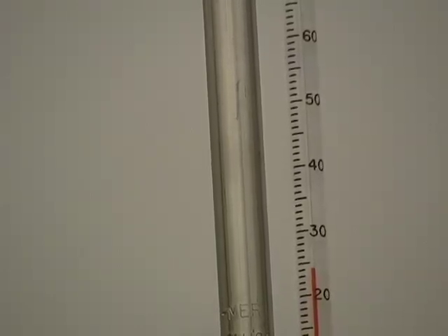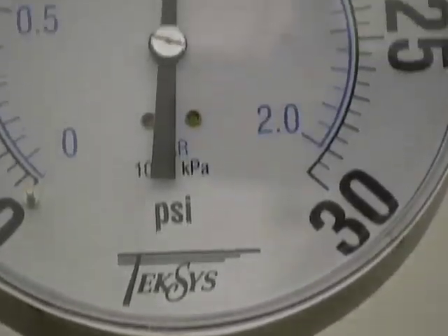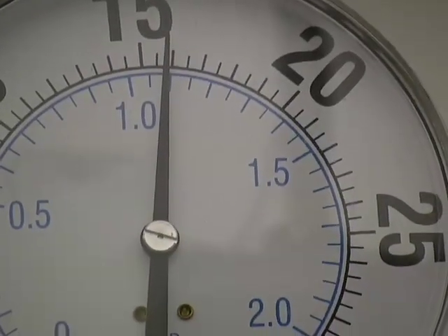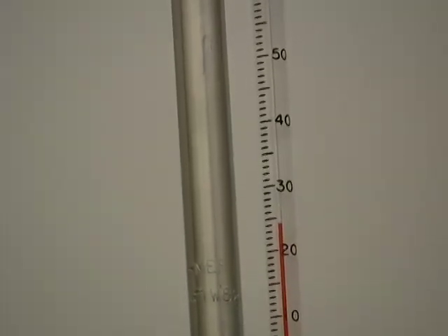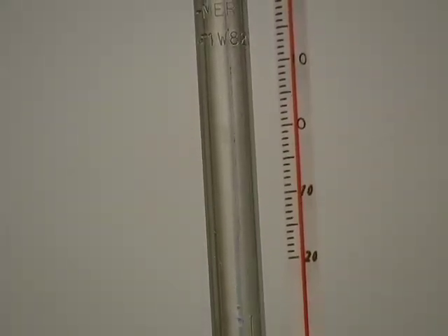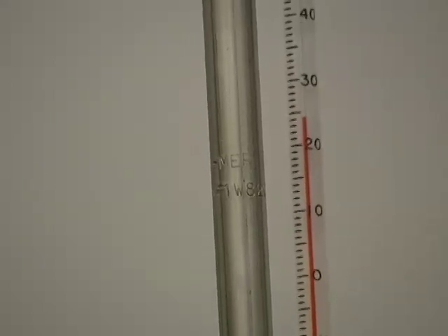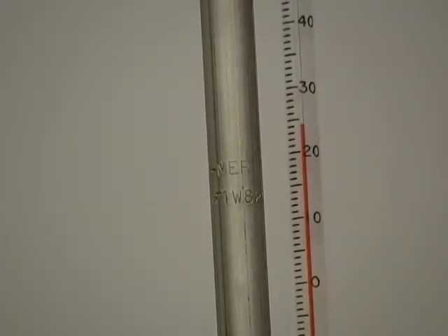I want you to take the temperature reading every 10 degrees Celsius and the corresponding pressure. Well, there may not be a lot of variation, but try your best. Now this is how I'm going to set up the scenario. When the temperature is 0, we will start there. I will move it down so that you can take the pressure reading. Alright? Okay, I'm going to now cover the bulb with ice so that the temperature reads 0. Let's see if that can be done.